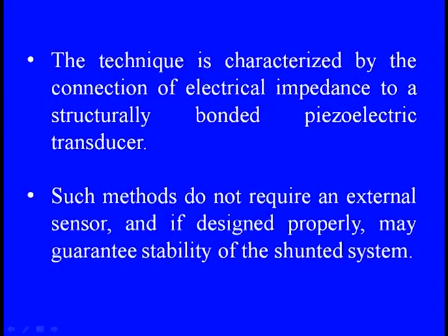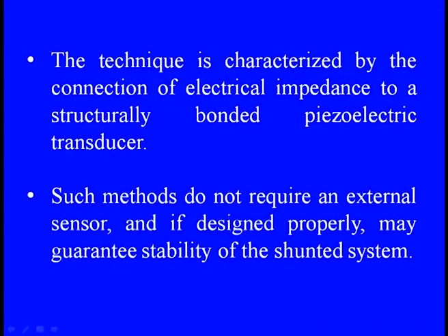And in this technique, you see here, we can simply characterize by the connection of this electrical impedance to structurally bonded piezoelectric transducers. So we need to check out the impedance feature and the mobility of this structure. Such methods do not require an external sensor. If we design these things, they can certainly give proper stability of the entire shunted system. So that is the unique feature of piezoelectric shunt damping, in which we can straightaway get the stability, actuation and sensing features from this piezoelectric part.